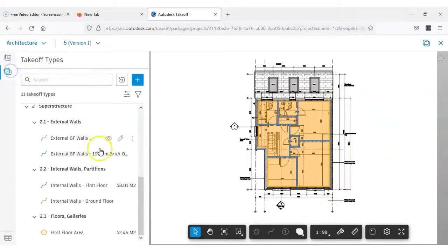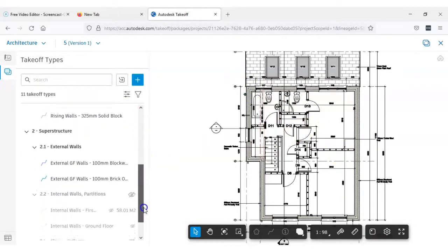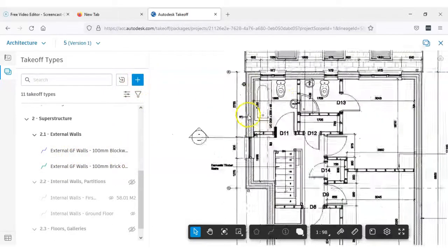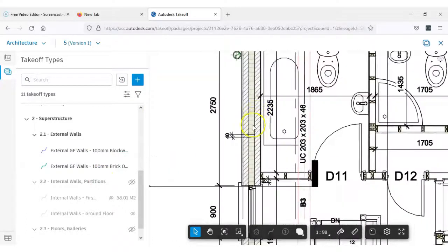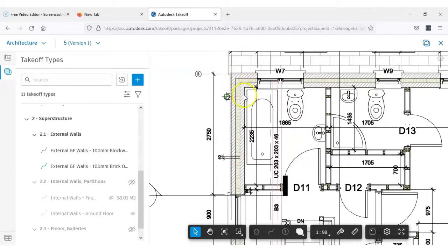So let's click back on our dimensions. You can click off these partitions and this first floor, to hide what's already measured on the first floor. And let's go ahead, scroll down here, and put in some measurements like this. We don't have brickwork. The only thing we've got here from an external walls point of view, and I'll get to the insulation in a second, what we call forming cavities, is blockwork on outer leaf, blockwork on inner leaf.